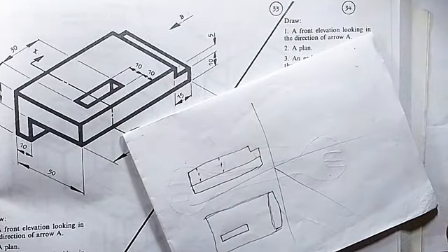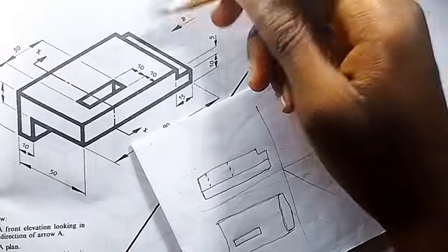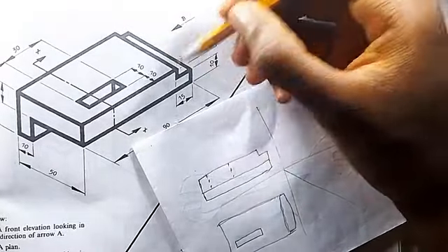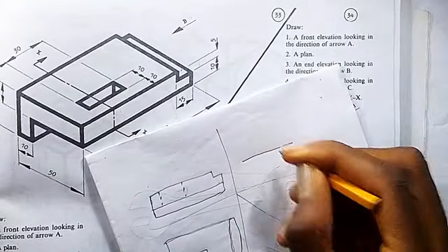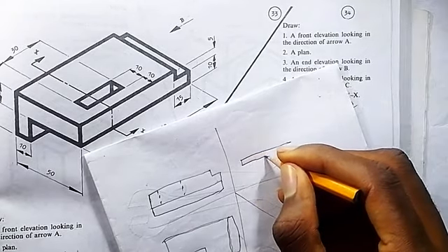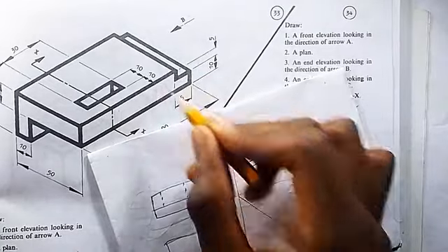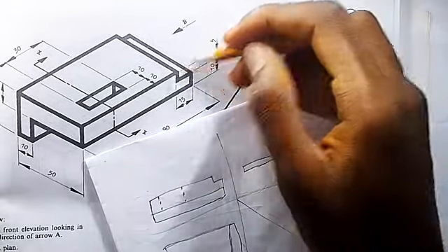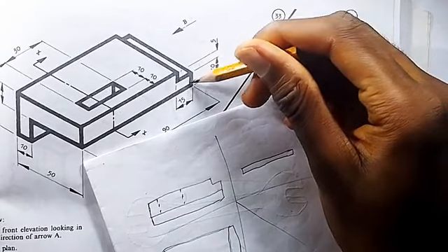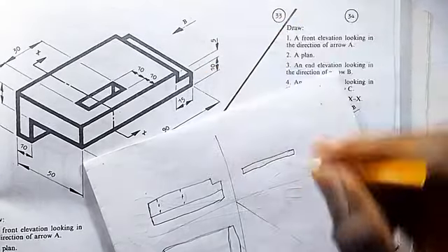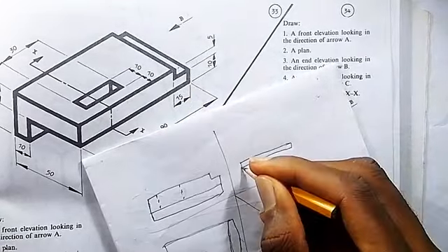So looking at the end elevation, what do you see? It's obvious. You can see this top layer looking at this side, which runs through to the end. So we draw that first at the end elevation. It comes down a little, so it corresponds with, in the front elevation, this part here. It corresponds with this top layer looking at the end. So what next can you see? You can see the lower part of the step, which is still this one here looking at the front elevation. So we draw that.